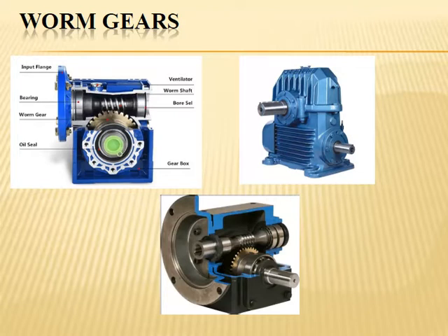This film may be very thin under boundary lubrication, hence it is necessary to ensure that the lubricant has sufficient oiliness property. Oiliness property is very important. Viscosity and the quantity of lubricant are very important in an industrial worm gearbox.